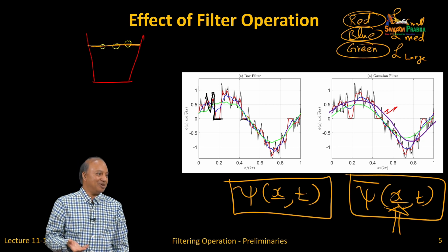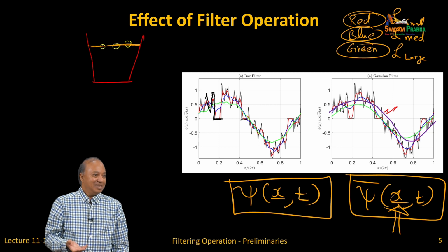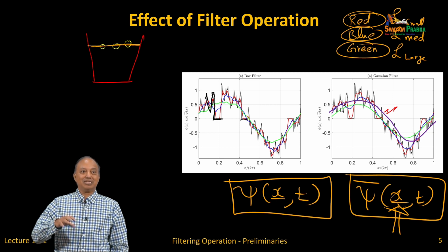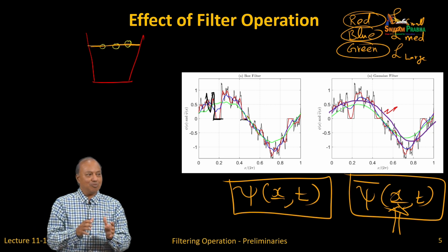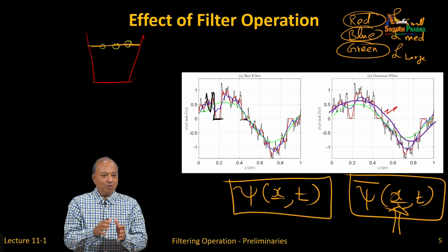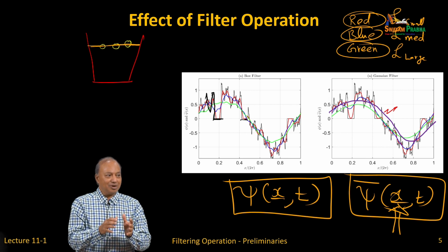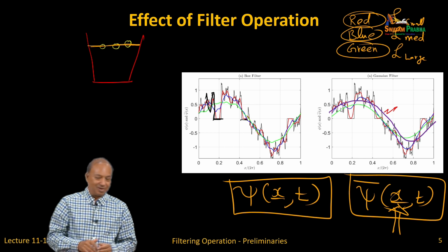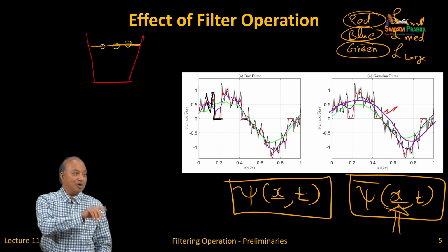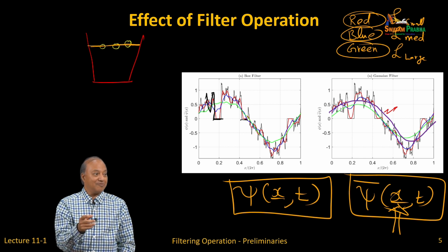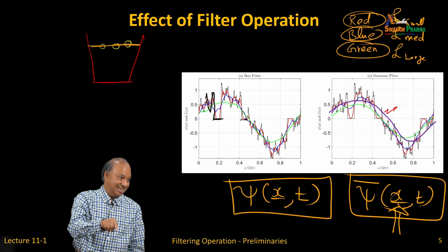Who are you averaging over? Now, on the other hand, if your filter width is bigger than the particle and your grid, so in particle resolved simulation, you want at least 20 or 30 grid per particle. In Euler-Lagrange, you want your grid so that you have 20 or 30 particles inside.